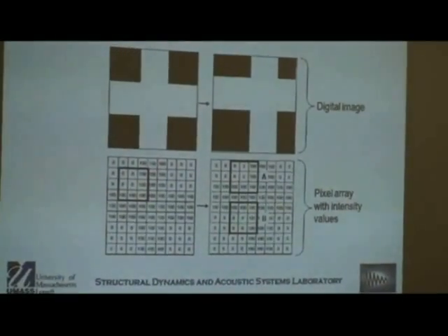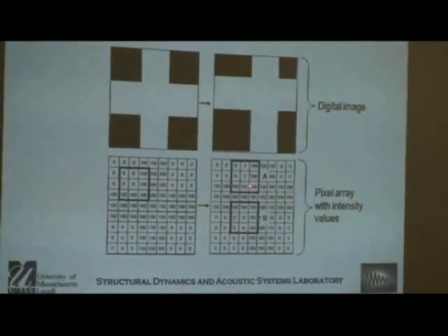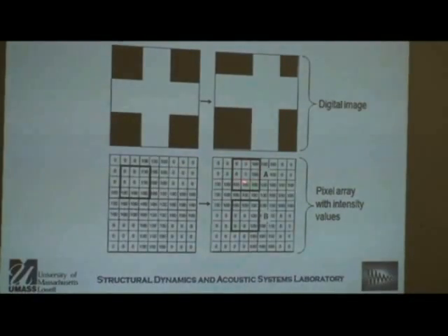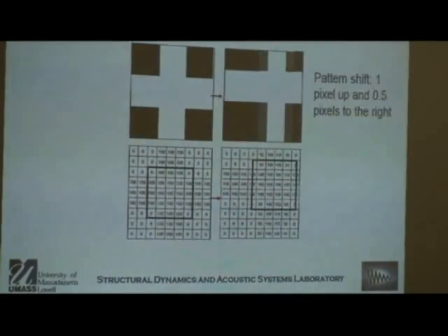Now if that facet moves over and up, I can take that whole image and correlate. I can look at all the different pixels and those numbers, and say this set of numbers is most correlated to that box. So what happened to the structure was that it moved over 1 pixel and up 1 pixel. With that, we can determine how a structure strains or how the deformation is made.